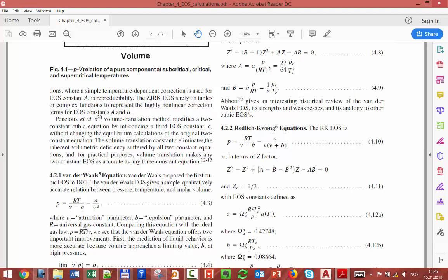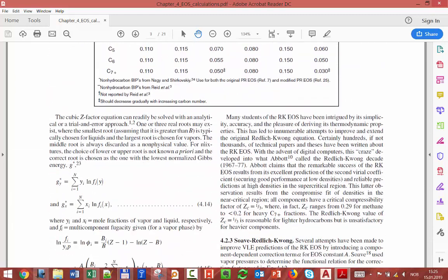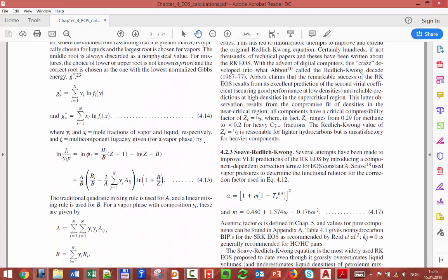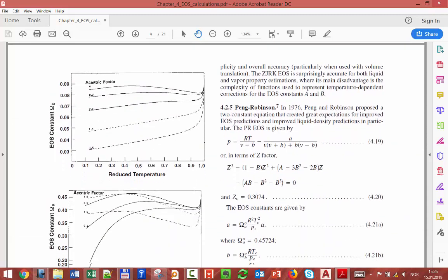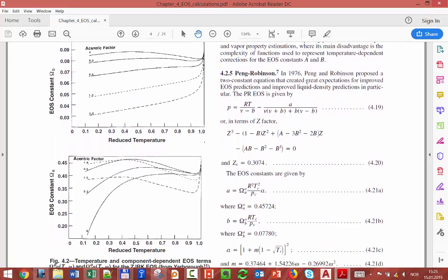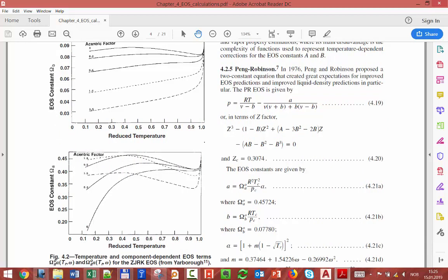You see here it's exactly the same, but now for V, I just use this expression. Add one more term. Then came a bunch of other people. Soave made an improvement on Redlich-Kwong. We are going to look at one of the most used equations. So instead of me presenting you all the different equations, all the different constants, the mixing rule, let's do it just for one. You get the idea how that's done, and then you're able to do it for any other equation.